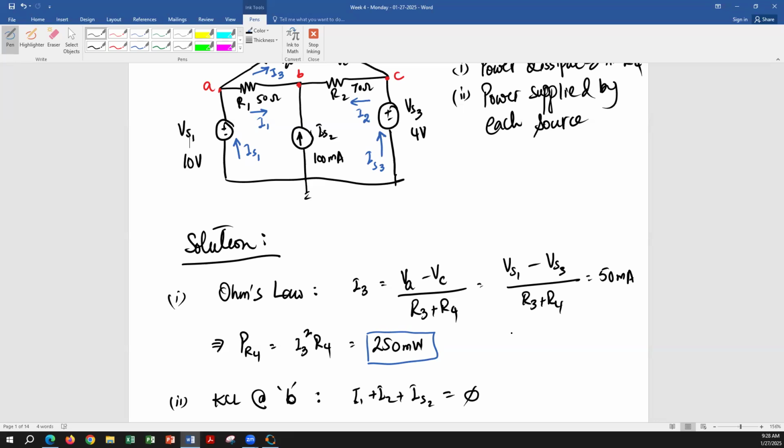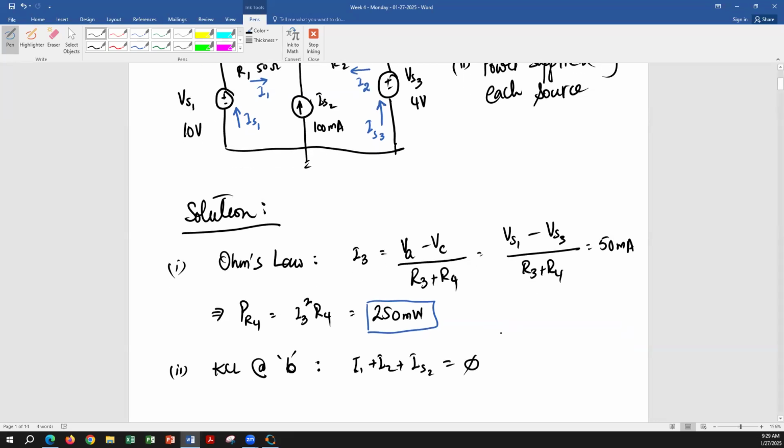Okay. Don't say A minus B. Say VA minus VB, because you are putting voltages, right? Okay. VA minus VB over R1. Good. So simply Ohm's law. Don't hesitate when you're applying Ohm's law. It's simple, right? VA minus VB over R. All right. Equation for I2.